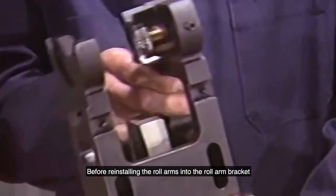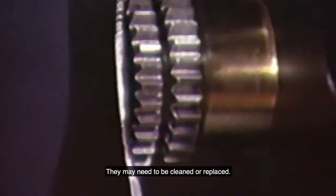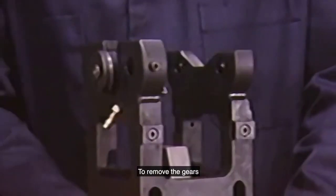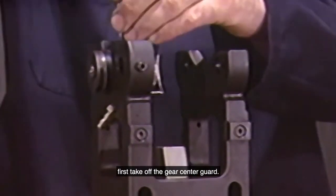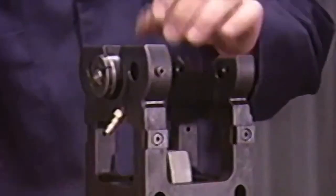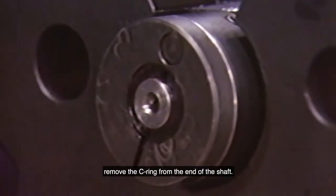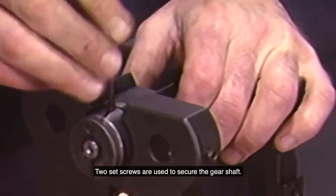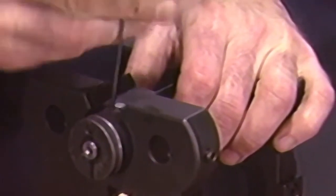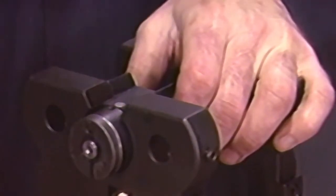Before reinstalling the roll arms into the roll arm bracket, inspect the compensator gears. They may need to be cleaned or replaced. To remove the gears, first take off the gear center guard. Loosen the adjusting collar cap screw. Using snap ring pliers, remove the C-ring from the end of the shaft. 2 set screws are used to secure the gear shaft. Remove the outside screw. The inside screw, which keys the shaft, should be removed next.